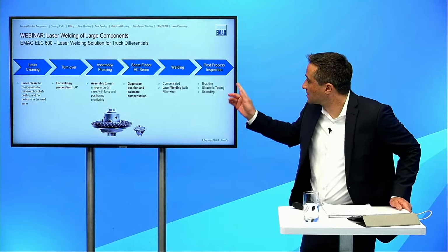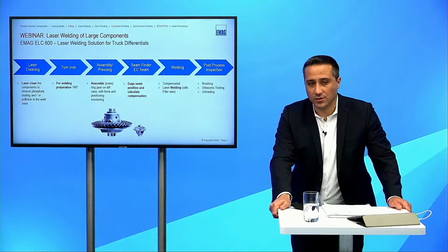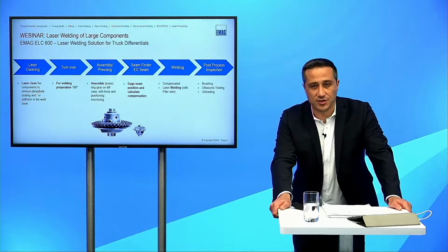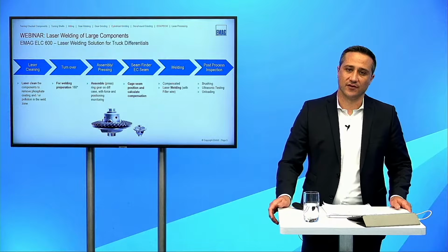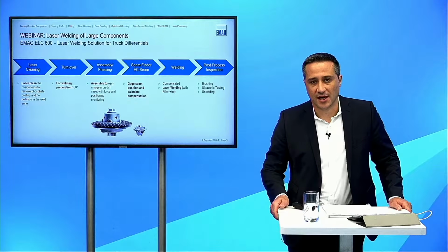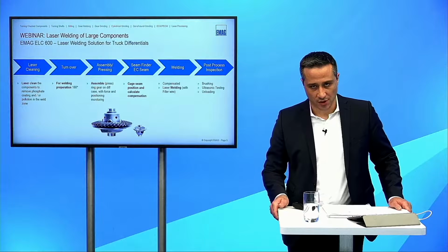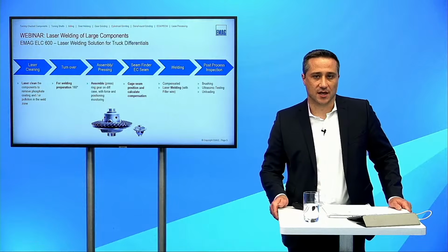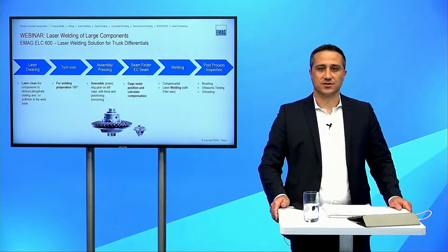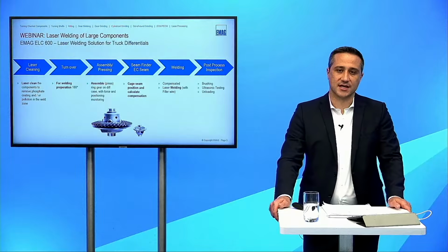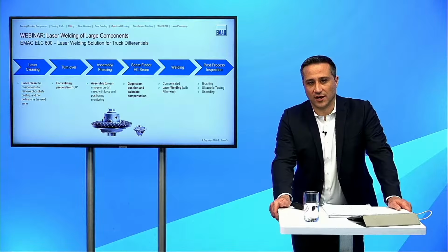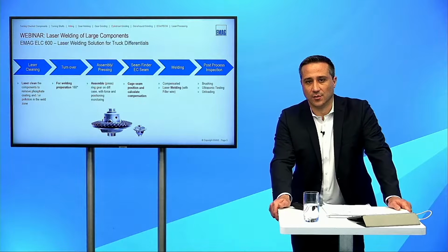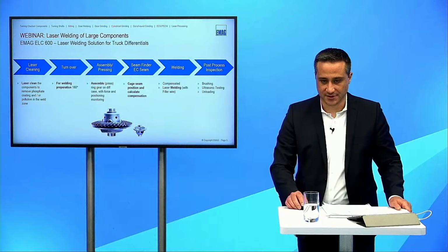And for sure, last but not least, we do have our post-process inspection, meaning we first of all make sure that there are no spatters on the welded surface, so we have an implemented brushing system, and afterwards we move the workpiece to an ultrasonic testing station which is controlling the workpieces 100%. This system is also developed by EMAG, software as well as hardware, and after we have checked the workpiece and it is going to be an okay one, then we move the workpiece out of the system.